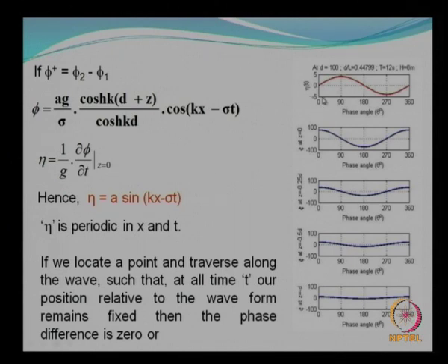Okay. So now I have just taken an example, water depth as 100 meters, wave period as 12 seconds and a wave height of 8 meters. So this gives me the relative water depth of about 0.44. Now in this slide I am just showing you the variation of eta here, and this is a sinusoidal variation. Now the variation of the velocity potential at z equal to 0, that is at the still water line, is shown here.